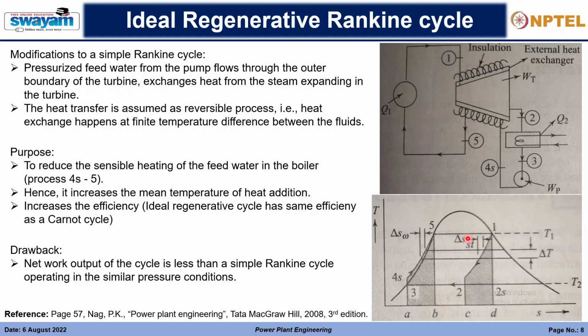But we are not using additional pumps now. We are actually using state 3 as the inlet to the pump. So state 3 to state 4 is the only pressure increase, by the pump. It is supplying, but the route of supplying the feed water to the boiler is now changed. It is flowing through this instead of flowing directly to the boiler.